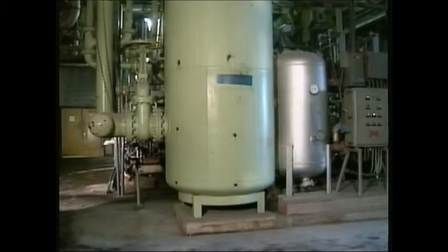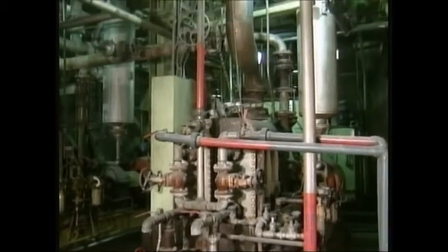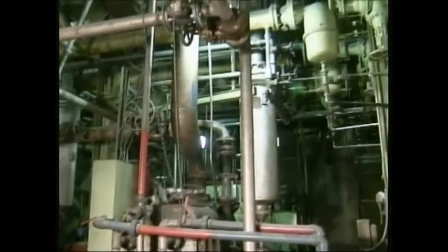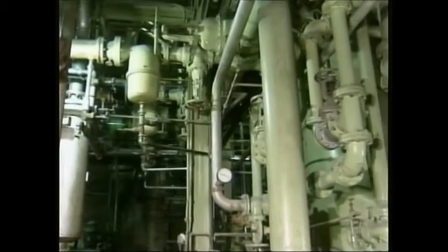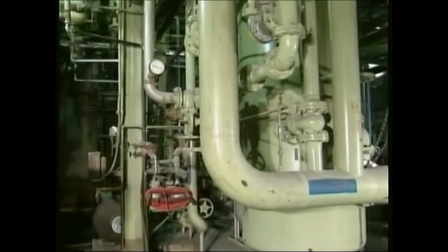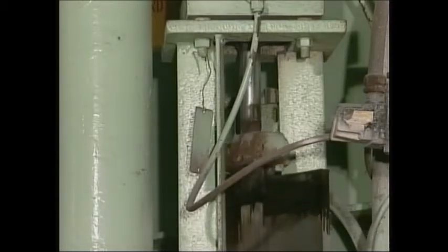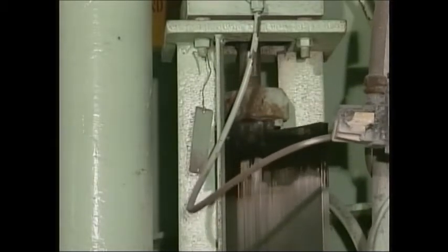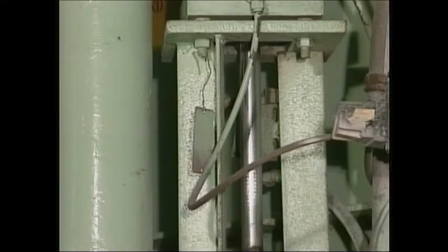In addition to height and mass, another factor which influences the potential energy of some process fluids is pressure. This air compressor, for example, increases the pressure of air and pumps it into the tank behind this piping, called an air receiver. Like pumping a fluid to a higher elevation, increasing a fluid's pressure requires the addition of energy to the fluid. The potential energy contained in the pressurized air stored in the air receiver may then be used to perform work, such as the operation of control valve actuators and other instrumentation and control devices.